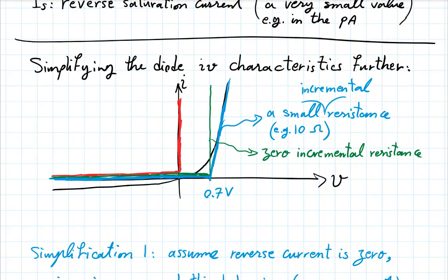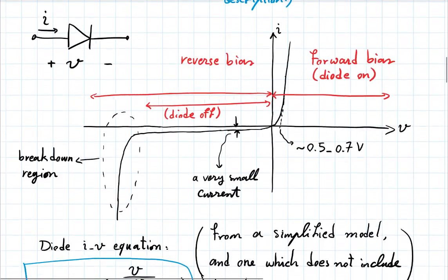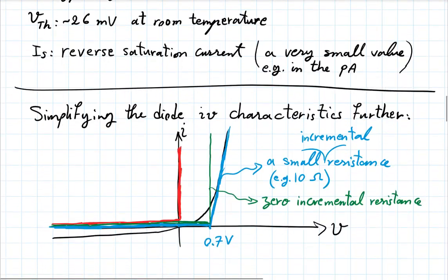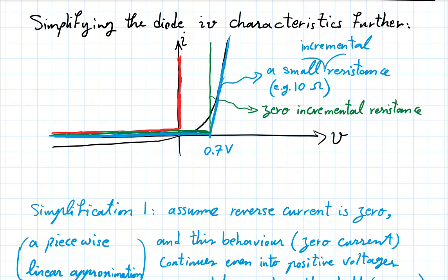This ideal diode is basically that switch that we talked about at the beginning, that if you wanted to operate in the forward mode, it would be like a switch that's closed. So basically, it can allow any current in the forward direction. And let's go back to our reference schematic here. Can allow any positive current in the forward direction, forward meaning where the current is positive. And essentially, your voltage, instead of realizing that it's slightly positive, you say, well, it's essentially 0. It's a very small amount, so I'll neglect it. So it's like a switch that's closed. And in the reverse part of the curve, when you apply a negative voltage, no matter how negative, the current is 0. So this is the ideal diode.